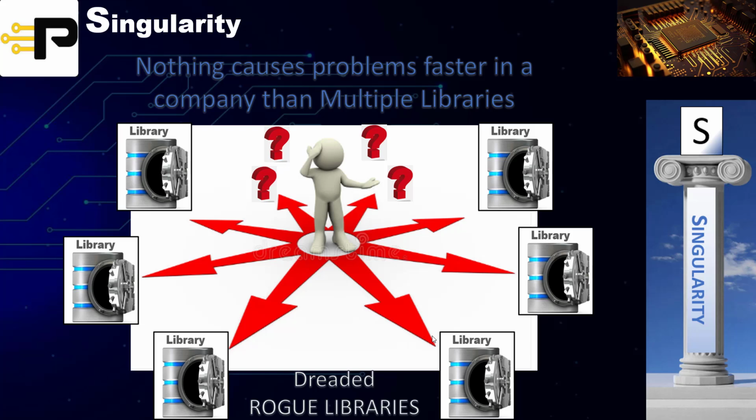And when I started investigating, I found out that the company was actually using 1,123 libraries, all different libraries, all different components in different states. And that was the result. We live in a world of cause and effect with PCB, and this was the effect. The cause was the fact that we did not have a managed single source of truth to work from.